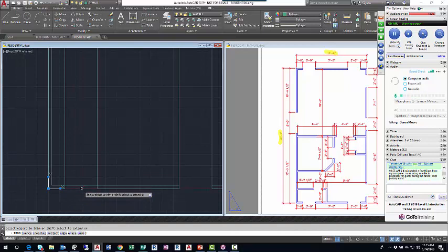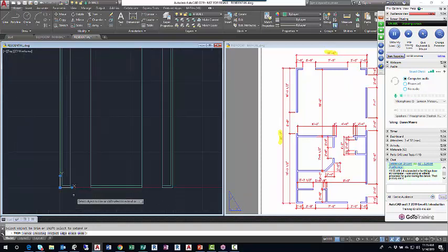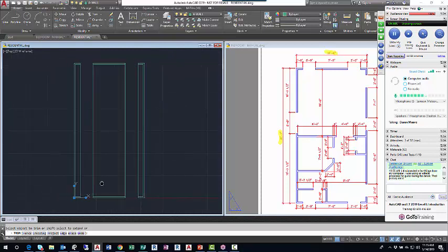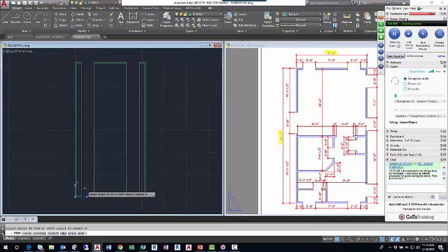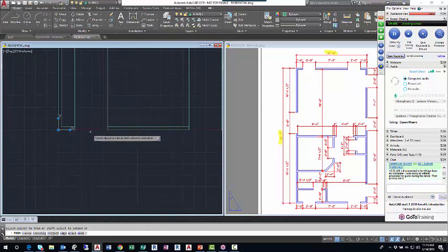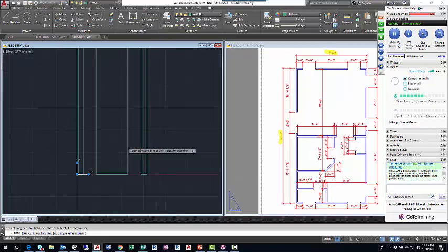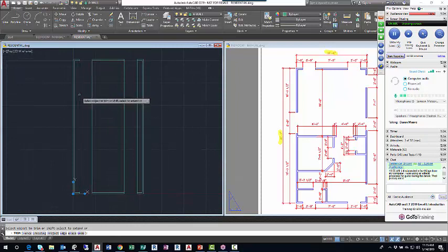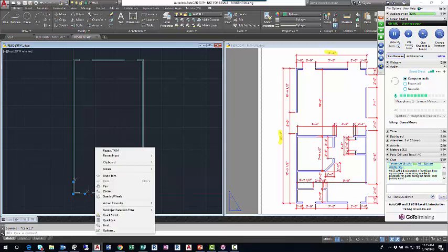So here I've selected the UCS icon. I did not mean to do that. It is selectable. It allows you to make certain changes to it, but I'm moving forward. I have created this window on the left side, window on the right side, window opening, and then I can left click on the cutting edges that I created earlier. I'll hit escape, and sometimes if hitting escape doesn't deselect the UCS icon, I might be able to right click my mouse. There might be a deselect option there.